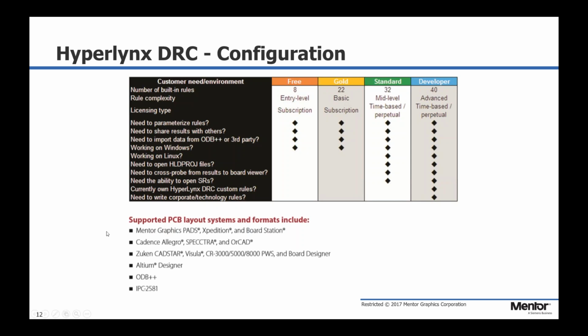That license is available. As for the supported formats, as we said, it's an independent tool, so it doesn't matter what PCB design tool you're using. Even if it can output an ODB++ or an IPC 2581 file, that's enough for it to be run in HyperLynx DRC.